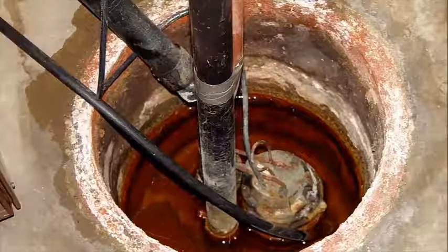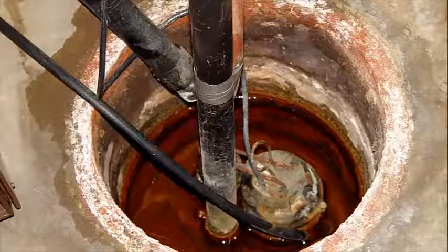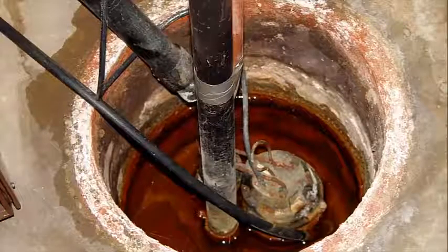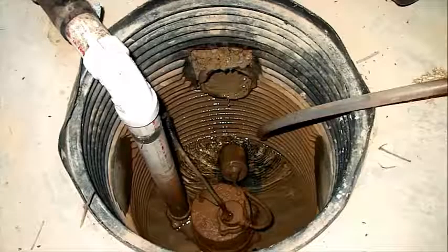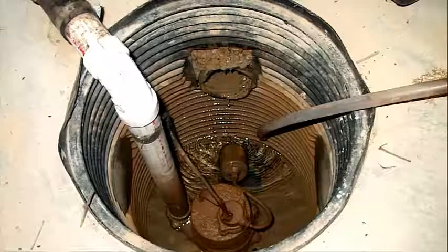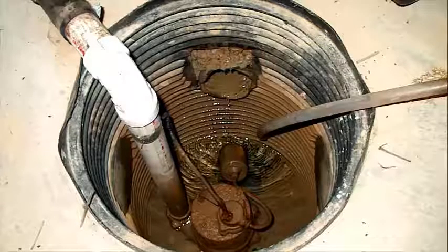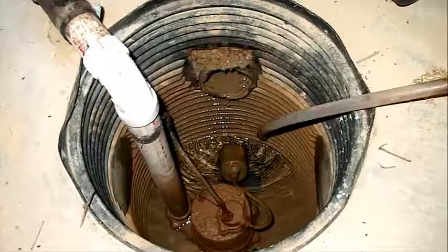Care and maintenance of sump pumps and their backup systems is very important, as is proper initial installation. Be sure to check manufacturer specifications on upkeep and battery life to ensure your unit is functioning properly. Simple measures, such as installing a sump pit lid or protecting the discharge line from freezing, may also help prevent system failure. Sump lids help keep foreign objects out and restrict pumps from moving, both of which can cause a switch obstruction and prevent the pump from starting.